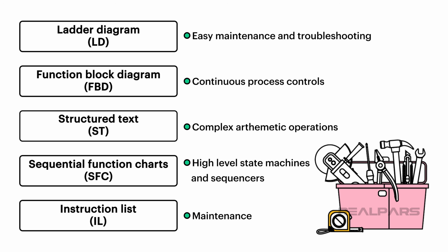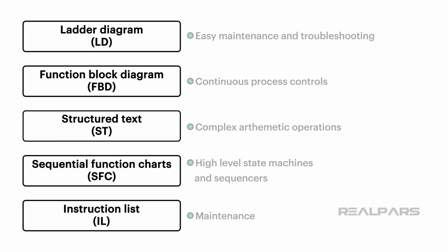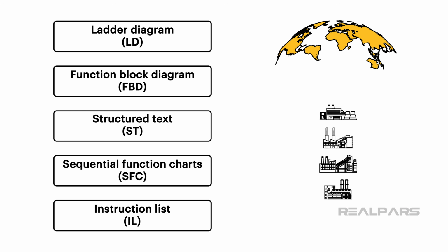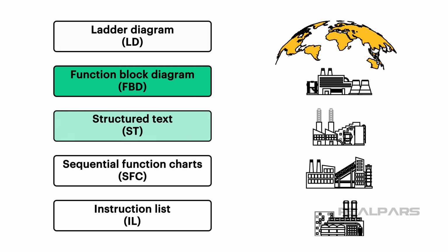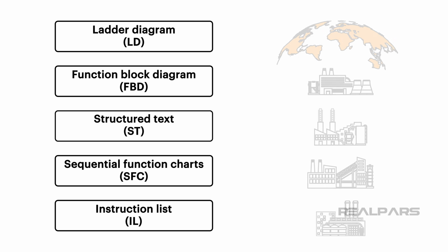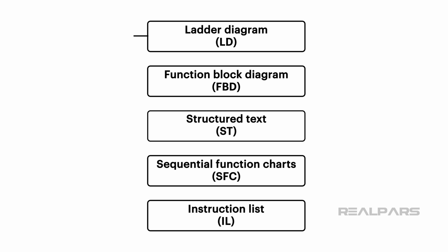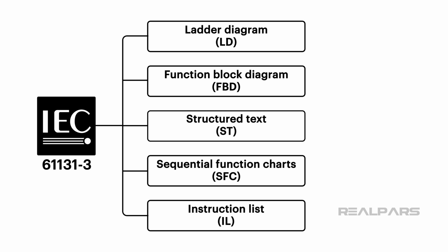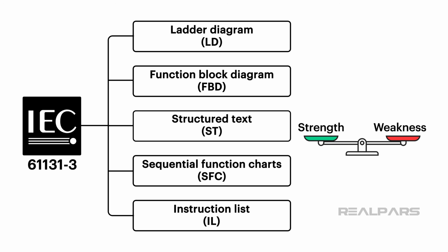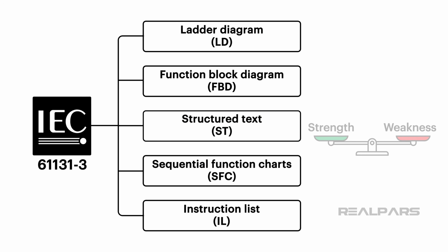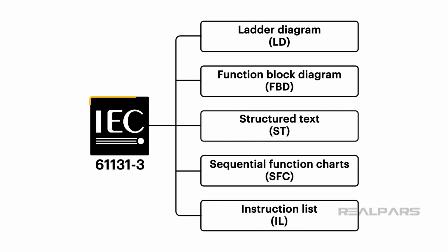applications. Making it even more difficult for us to answer that question is the fact that different programming languages are more popular in some countries and industries than others. So the best PLC programming language for you to learn may vary depending on where you live and what industry you're interested in. In this video, I will explain the main features of the 5 IEC 61131-3 programming languages, along with their strengths and weaknesses, and where they are used to help you decide which PLC programming languages to focus on first.